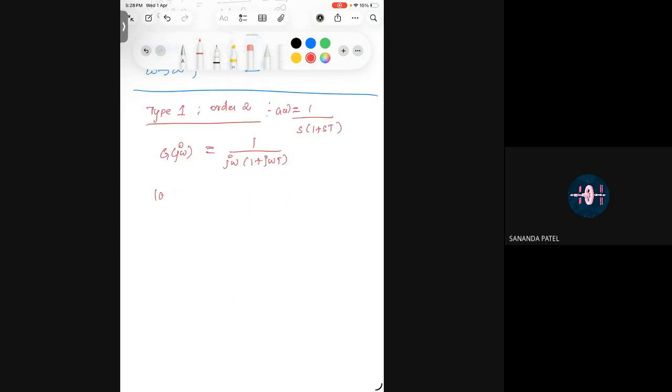So the first thing I would do is calculate the magnitude for this. Okay. This is in the other format, right? I can do it like that, okay? So you don't need to multiply and divide. For now, I am keeping it as it is. So this will be j omega plus j squared omega square T. So it will be minus 1 omega square T, or minus omega square T. The real part is minus omega square T plus j omega. Only j omega, no T here, right?